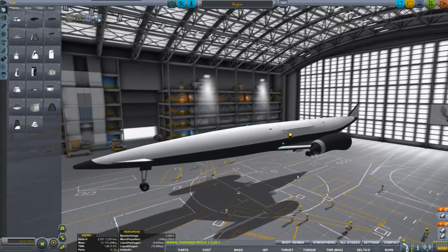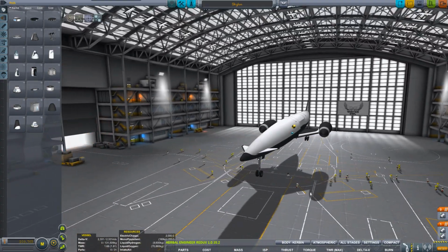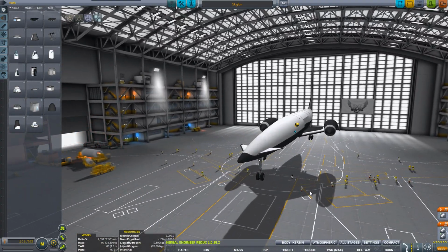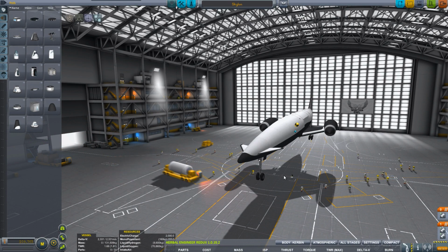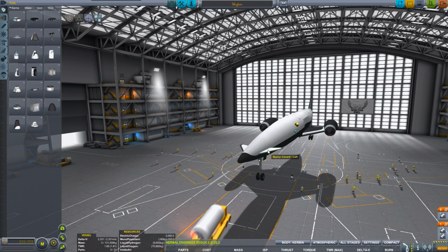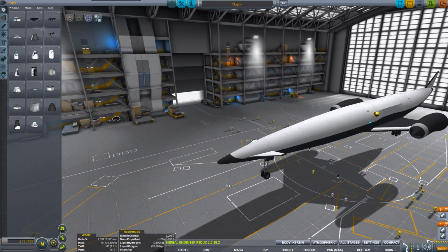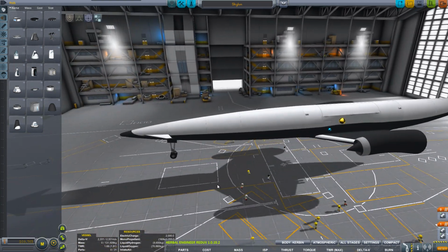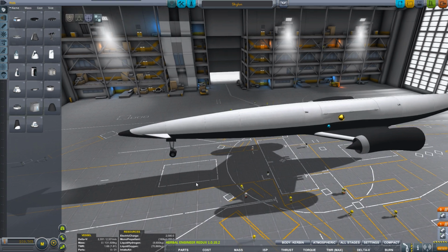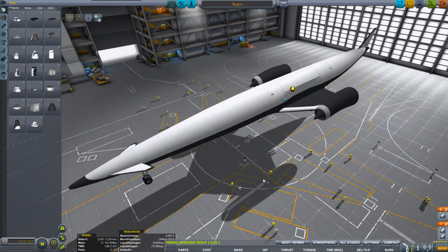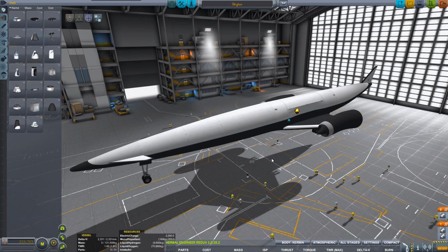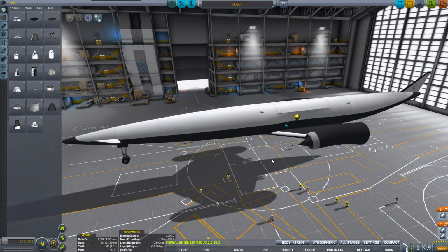Now, I believe that the real vehicle is intended to work through this as it's just going to be very, very smart. It has a great deal of very precise control over these canards working as the elevators. So even if it doesn't have aerodynamic stability, this will be able to give it stable enough pitch control in order to work. And of course, it will have that more efficient lift coming from having canards instead of the more traditional cruciform tail and back. However,